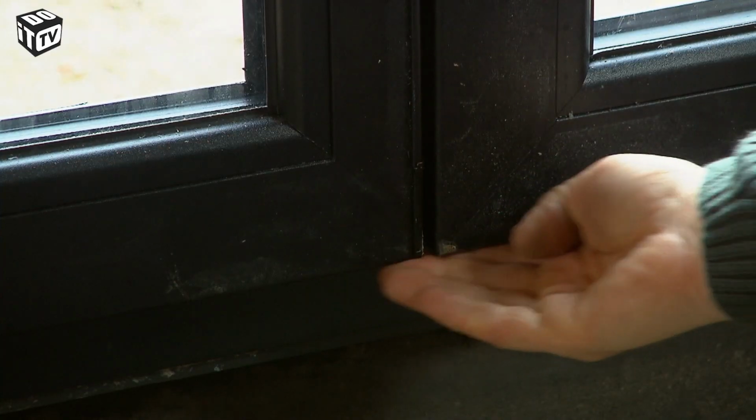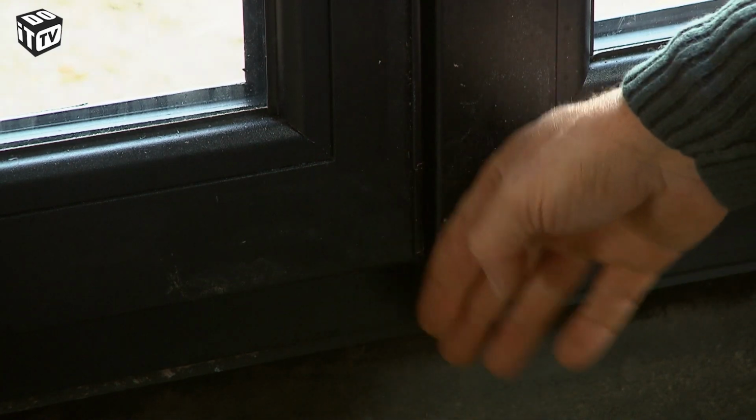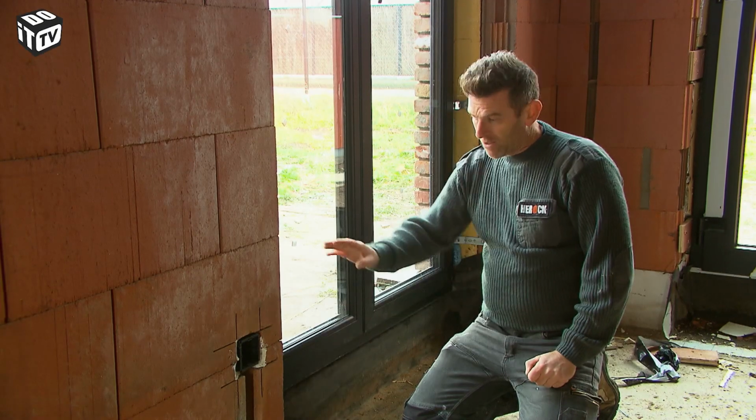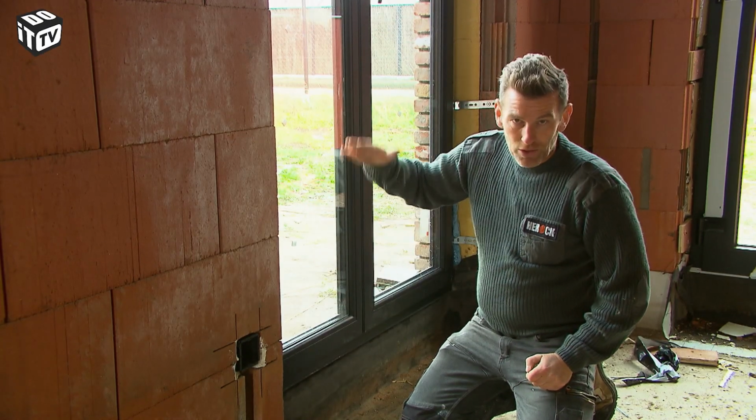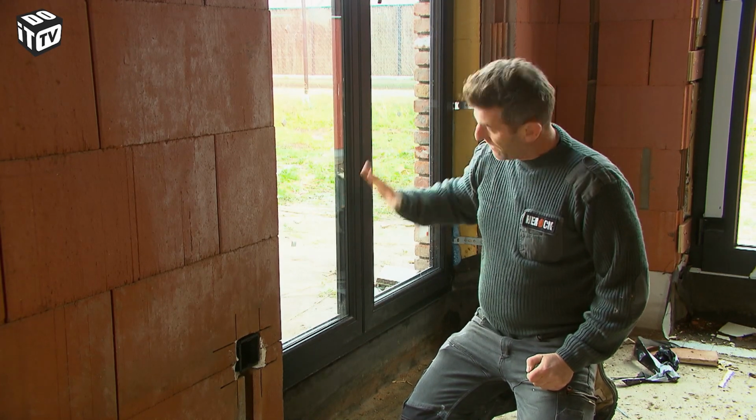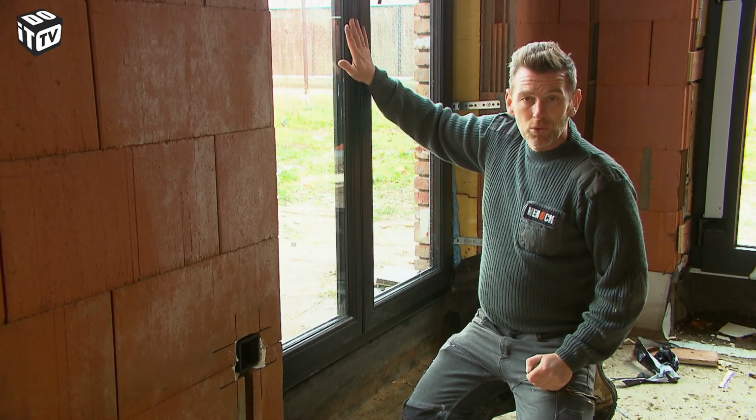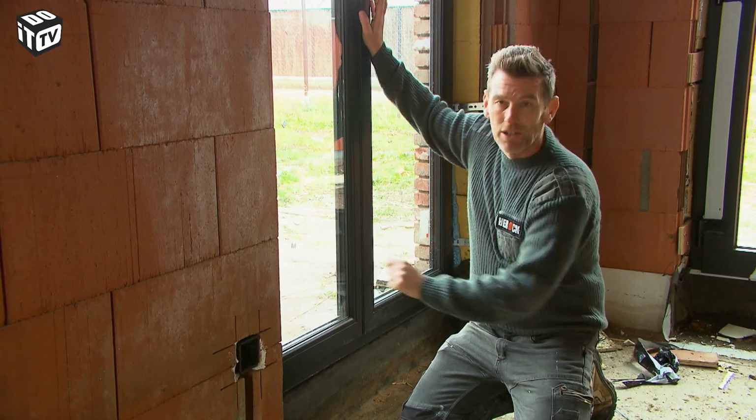The two wings of our window are not perfectly aligned with each other, however. With the hinges we can easily adjust all that, both in terms of height and left-right direction. We'll open the window, both wings, removing tension, then adjust it properly.